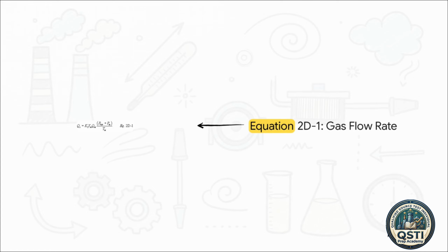K1 is a constant, specifically 0.3855 degrees Kelvin per millimeter of mercury for metric units, or 17.65 degrees Rankine per inch of mercury for English units. Ym is your test meter calibration coefficient, and Qm is your test meter volume flow rate reading. You multiply that by the sum of P bar, your barometric pressure, and PM, the test meter average static pressure. Finally, divide all of that by Tm, which is the absolute test meter average temperature. You've got to understand how these variables interact to correct your volumetric flow rates. It's a fundamental requirement for the exam.